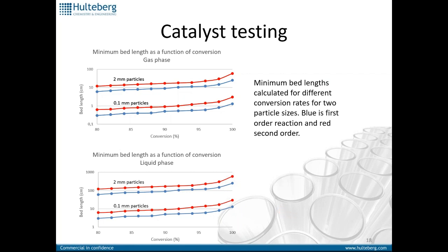So make sure that you can avoid concentration gradients in the axial direction, and basically what we're checking for here is how close to a plug flow reactor we actually are. So if you have a low relationship between the actual dispersion and the linear velocity, you will have more tank reactor behavior than a plug flow or ideal plug flow reactor. And that's what we're checking for here.